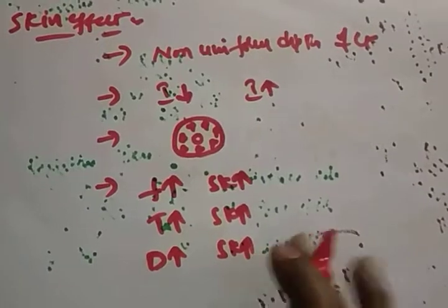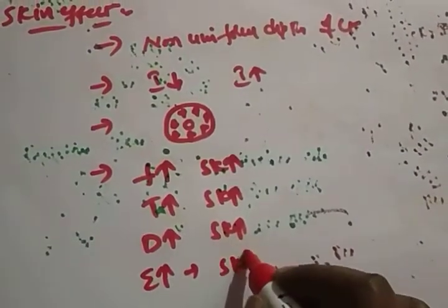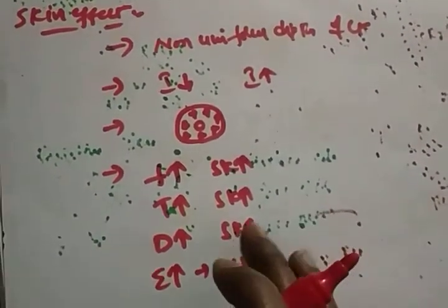After that, the type of materials used. If a material has high permeability, the skin effect is high. So we always look for low permeability materials to reduce the skin effect. As a design consideration, using a solid conductor on the core will definitely increase the skin effect.